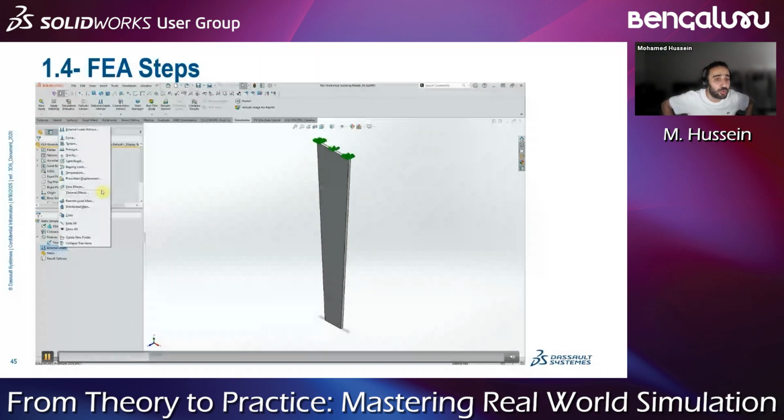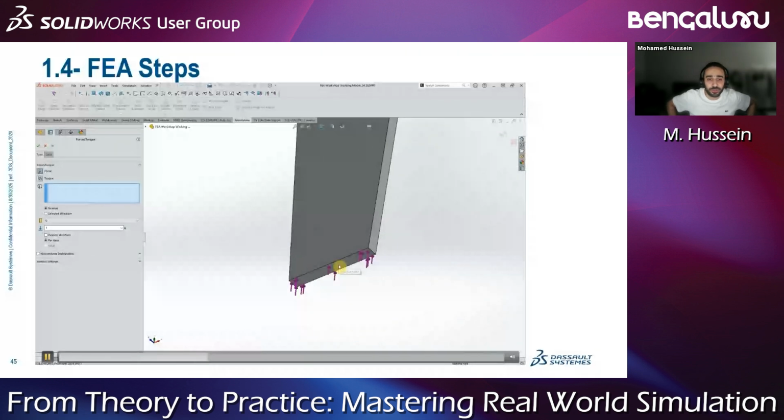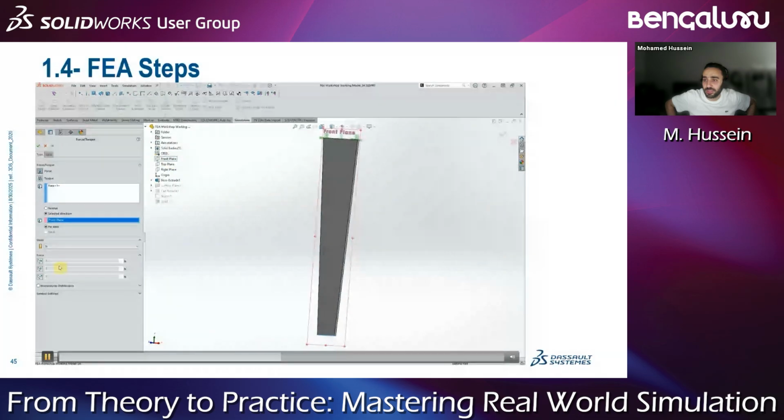I can also import my flow or thermal effect from another simulation in SolidWorks. I can import it here, which is defined as a kind of fluid-structure interaction, FSI. I choose this face, and I will select the direction. I will say that the value here is custom.